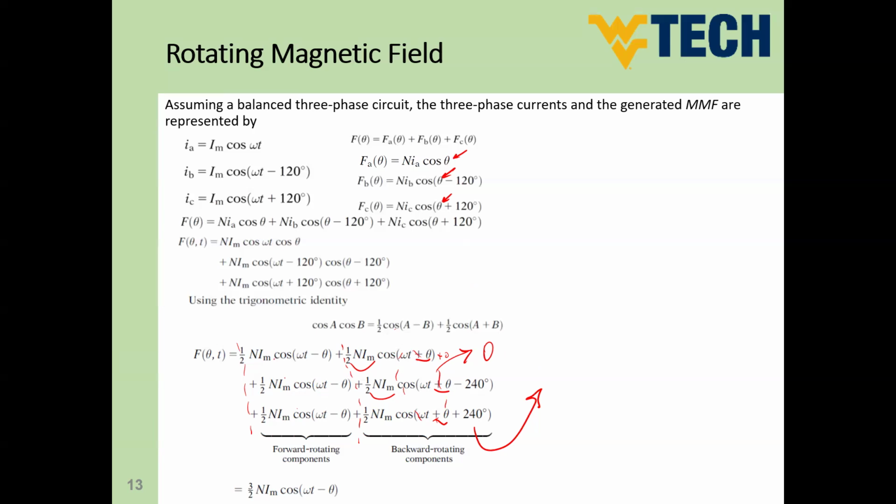If we don't have the 120 degrees phase shift, if we have 2 phases, not 3 phases, or a single phase, not 3 phase, for sure the magnetic field is not going to be rotating. And a rule for any rotating machine, guys: no machine will rotate without a rotating magnetic field.